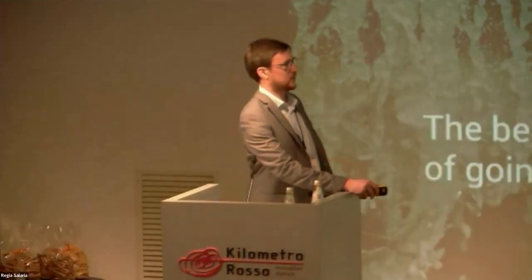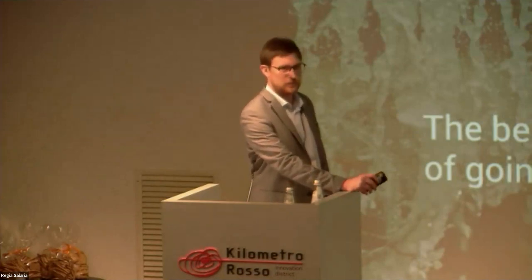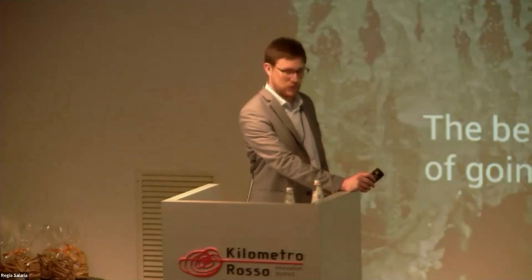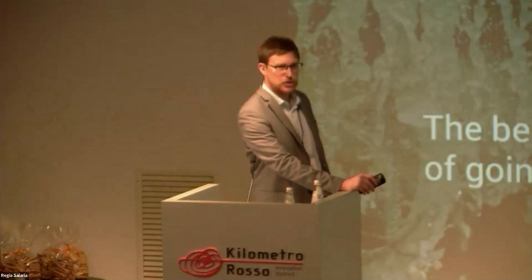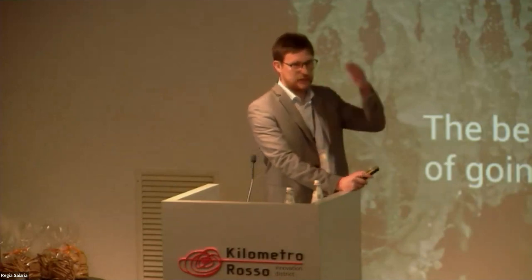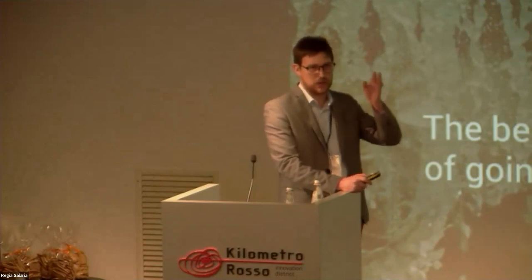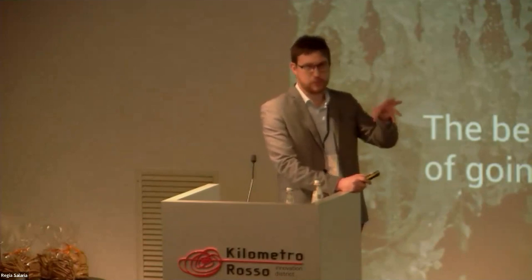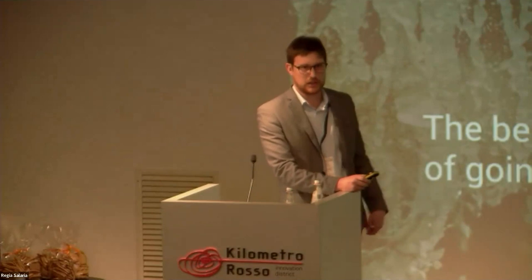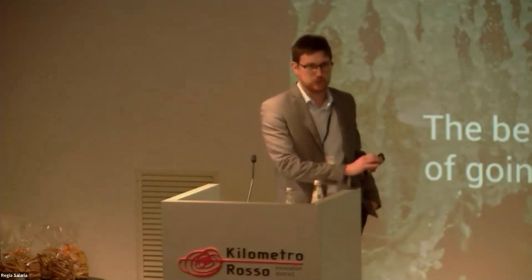Hello. You mentioned steady state simulation. So I assume you use a constant power input. Is there a way to add power as a function of time, so you can run a kind of engagement? Okay. Yeah, it's possible. You can create a table, an Excel file with time and power, or volumetric power, and then you can input it. So you can do it. Okay.